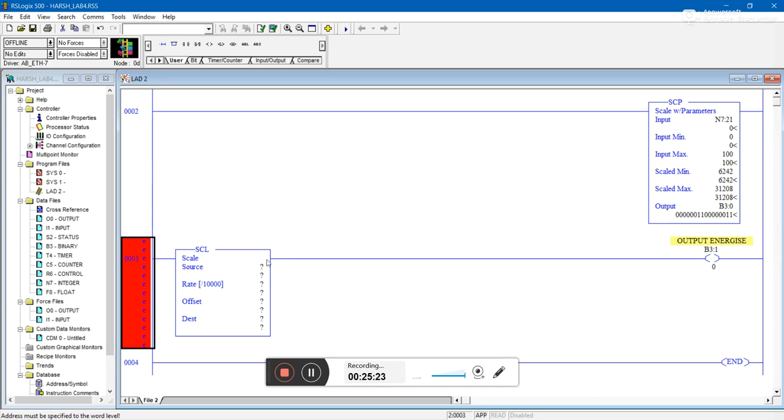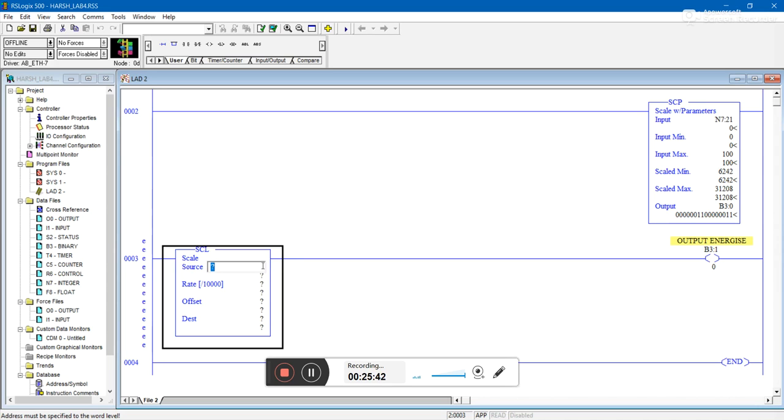Basically, if you have a valve open, you don't know how much it is open. The sensor that is giving you the values does 4 to 20 milliamps. Then for what value of current, how much the valve was closed, can be determined using this one.